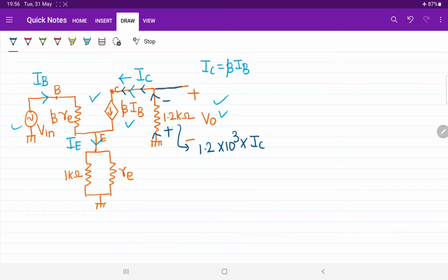And the polarity is this is plus, this is minus, because for a resistor, current entering point will be plus, leaving point is minus. I am repeating, it is standard for all other upcoming circuits also. Once you understand this one clearly, then everything will become easy. So try to understand. Okay sir.